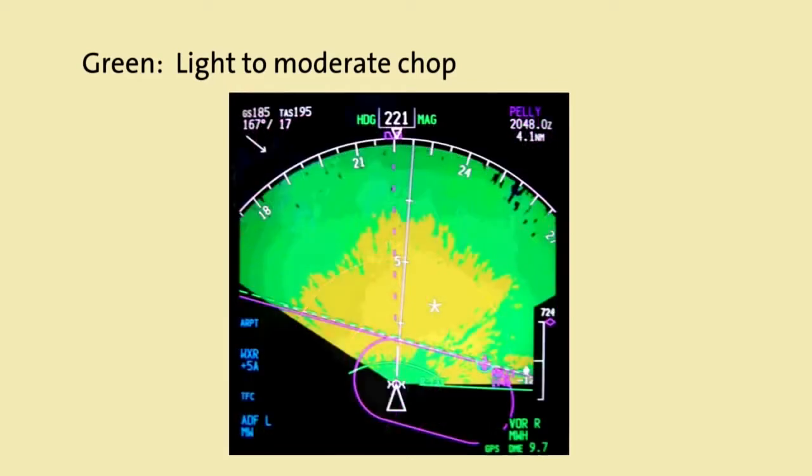At lower altitudes, there are occasions during certain unique meteorological conditions where the display may turn completely yellow or even red, which is sometimes called redout. In this instance, the aircraft is right at the freezing level, and melting snow has formed an area of strong reflectivity, turning the display yellow, even though there is very little turbulence. A similar situation sometimes occurs during monsoon rains, where heavy rainfall rates produce very strong reflectivity.